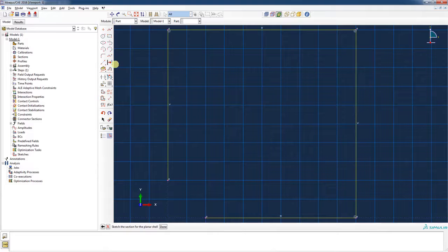And we're going to create an arc. I don't know if you can see it very well, but the little arc symbol has a 1, a 2, and a 3 in it. That's the order of identifying the points. Number 1 is the center of the arc. Number 2 is the top of the arc. Number 3 is going to be the bottom of the arc. So I'm going to click that and then get that point, that one, and let's try this one.